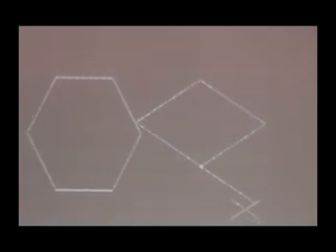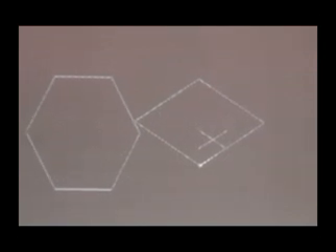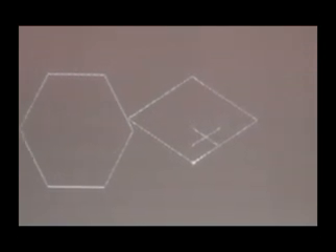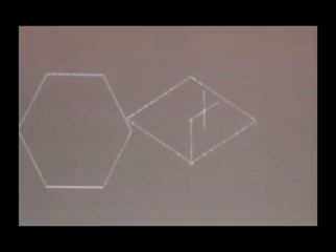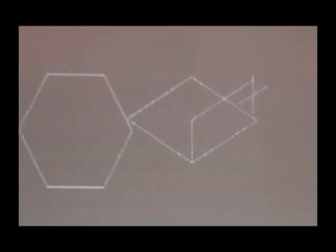This is the iso plane. Suppose I want to raise the height of the isometric view along the z-axis. I typed F5, and it goes to another axis, the z-axis. Along that I raise a height of 10 mm. Then along this I draw 20 mm.